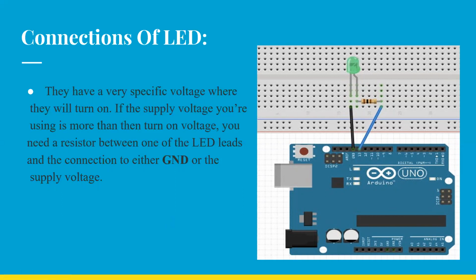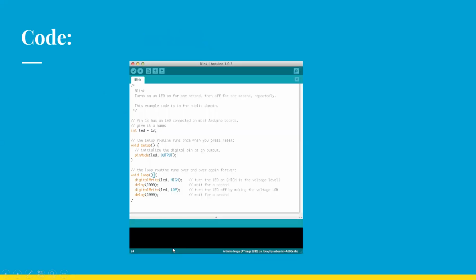But running your Arduino this way lets too much power flow through the LED. So to overcome that, we will use a resistor. Then we will connect the resistor to the positive, which is a 100 ohm resistor, as shown in the figure.